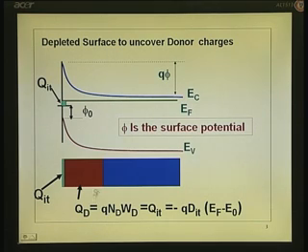If Q N_d W_d is constant, when D_it is large, if there are more states in the surface, E_f minus E_0 will actually be smaller. That means at higher D_it values, the Fermi level gets closer and closer to E_0, because a smaller gap between the two is sufficient to supply those charges. E_f minus E_0 into D_it: if D_it is large, this gap need not be large.